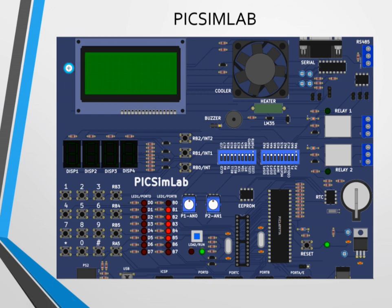Next, we have timers. Timers are one of the most important workhorses for an embedded programmer. Every application that we design will somehow involve a timing application like turning on or off. So PIC16F877A has three timer modules, that is timer 0, timer 1, timer 2. Timer 0 and timer 2 are 8-bit timers and timer 1 is a 16-bit timer. In our program we have used timer 2.